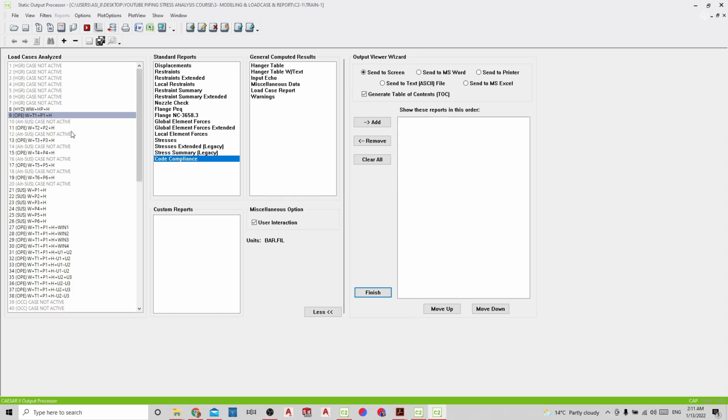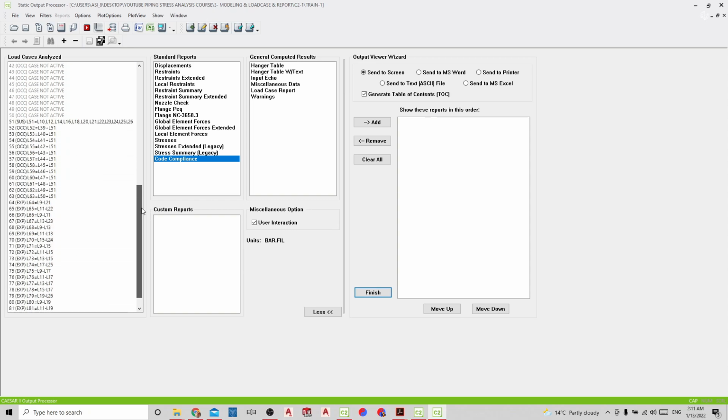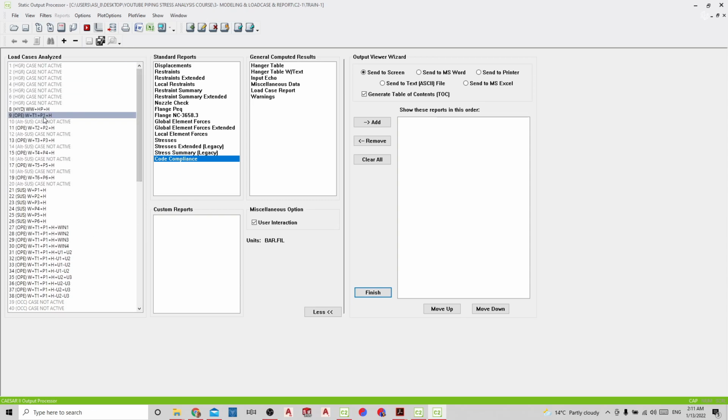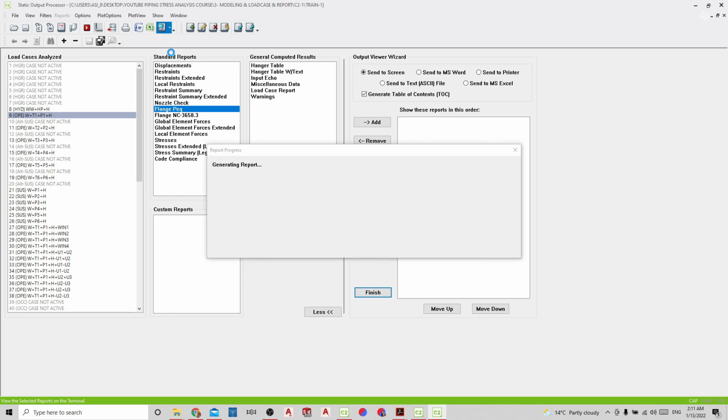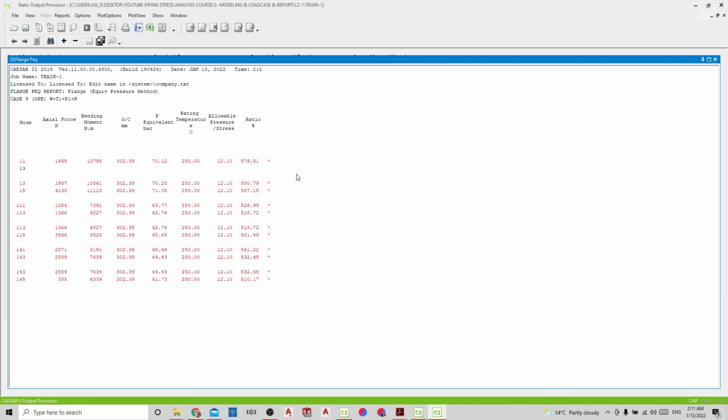What we first do, as I told you, is check if I have anything over stress. If I don't have anything over stress, I go to make the frequency check. For the flange check, I use the normal operating condition and check whether I have overpressure. Here I will have an overpressure. I left it to show you. See, the numbers are big. These big numbers mean that we selected the wrong flange rating, in case the material engineer was mistaken.